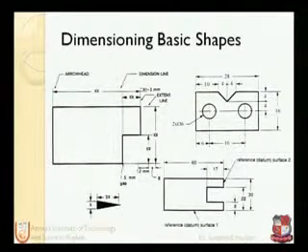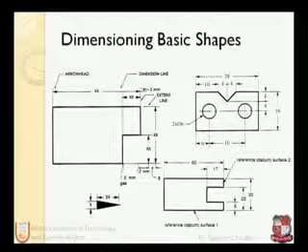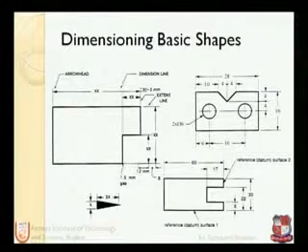On the bottom right hand side we can see the parallel dimension system. One datum is defined, and from the bottom 8 mm, 22 mm and 30 mm can be shown. For both chain and parallel dimensions, we can use either system, the aligned system or the unidirectional system.